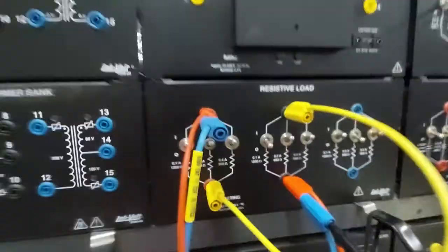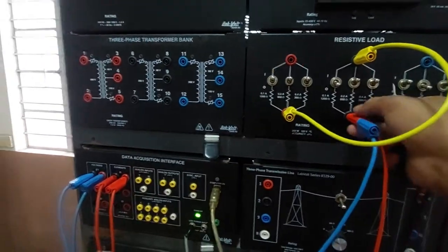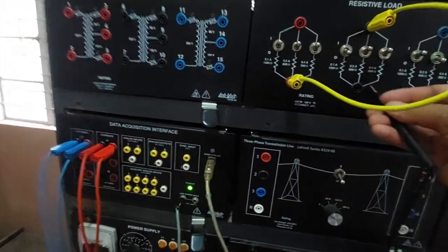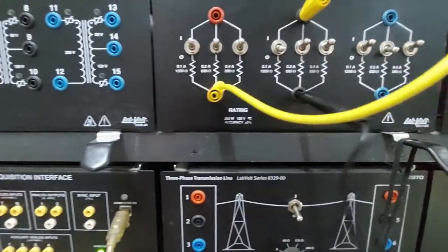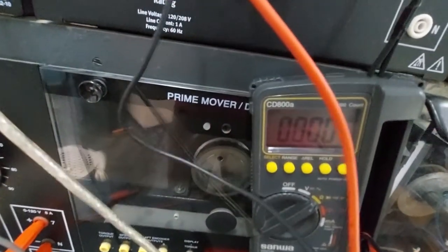After getting the value of our voltage and our current, let us manipulate those readings in order to solve for the value of resistance, and then let us verify it using our multimeter. Always make sure that the power supply is turned off or there's no power going to the resistance when you are getting the value of the resistances that are connected into the load.